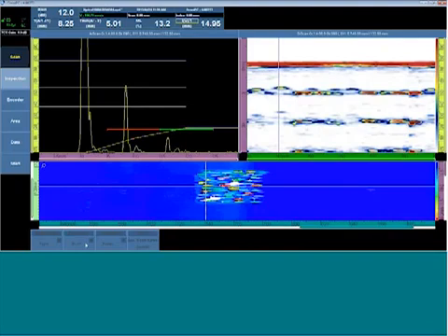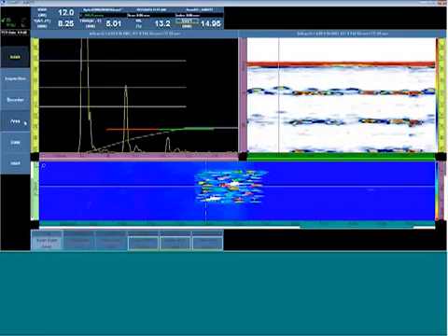So if we look at the scan menu, in this inspection, we've selected raster scan, and now we have to assign encoder 1 and 2 to the scan and index axes. So instead of just having one encoder, now we would have two, and they would both be configured independently with a resolution and an origin position. In a one-line scan, we only saw available the configuration for the scan axis start, end, and resolution.